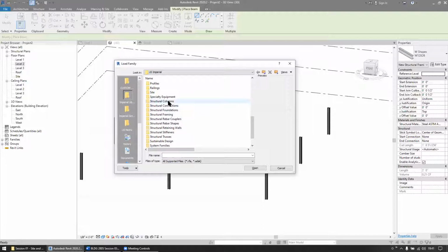It's not a column, so we're using the beam tool now so you folks can see place beam. So you got to remember to keep your head on your shoulders and not accidentally go into the structural columns folder. You know, I've done that so many times. You go into it, you're not paying attention, and I've started up the beam tool, and then I go into the structural column folder to find something. Like, what? Wake up, dude.